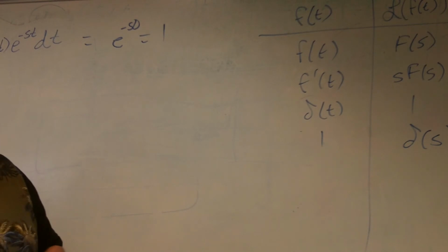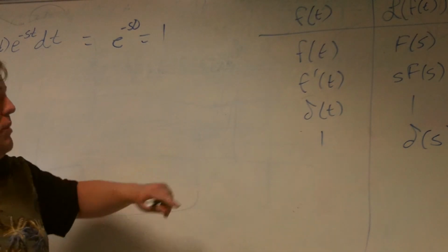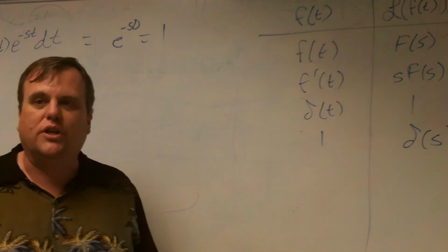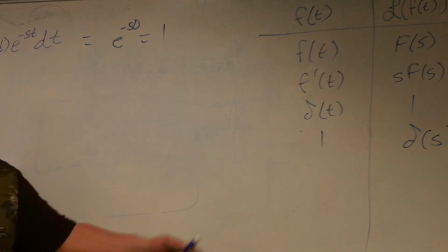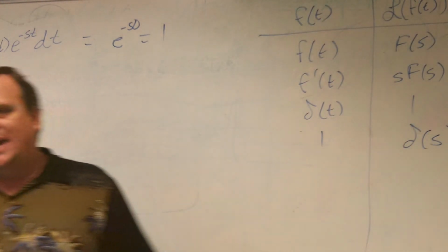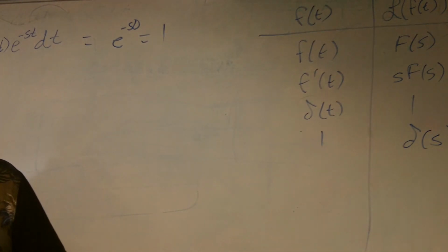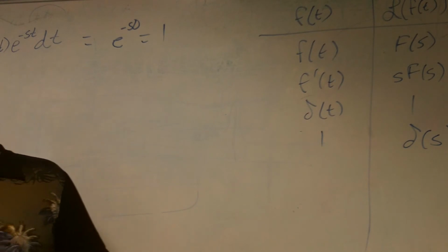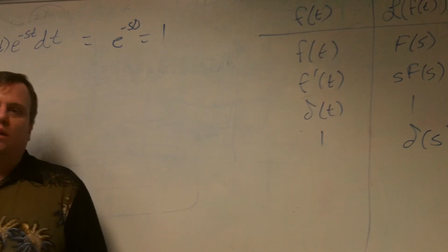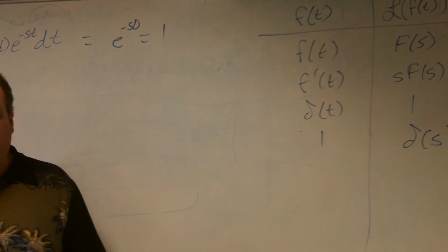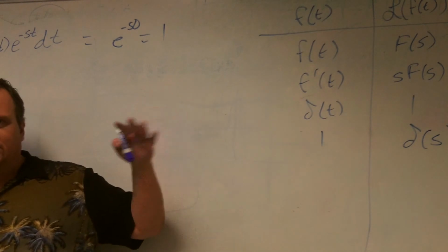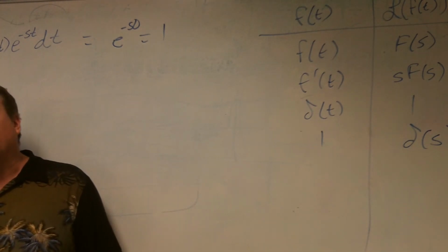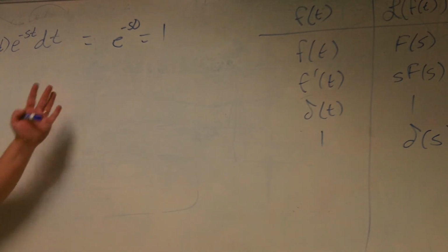So in the extended case, that would actually damp out at the ends of infinity, right? Yeah, the main lobe will continue to stretch and push out to infinity. But it would actually damp at infinity, even if that was a crisp 100%. Technically, this is 1, but you've got to have that it converges. So 1 times e to the minus st, you must have that your s is able to dampen out. That's why I've got that minus sigma. The minus sigma allows me to dampen, because 1 is a constant. 1 times e to the minus sigma t is going to give me a function that damps down to 0. If the net product didn't damp down to 0 at infinity, you would have an infinite integral and it wouldn't converge. So that was part of the fun of this.